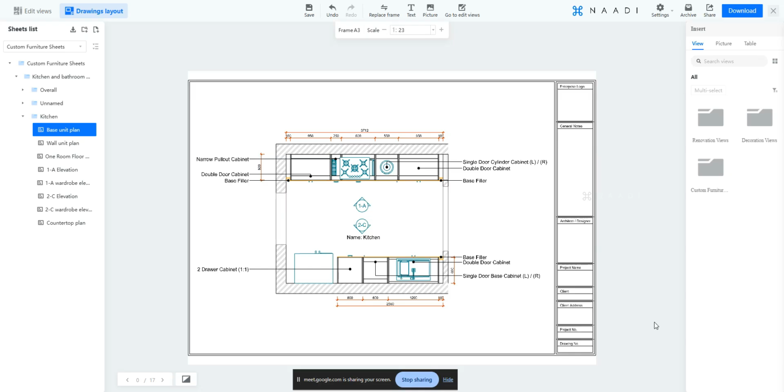So if your organization has a pro license ID, you can just share your 2D sheet template with us. That 2D sheet template needs to be shared as a DWG file. And if your sheet template has your organization logo, make sure that the logo is also a CAD logo. Please don't add it as an image, because the 2D sheet template in the backend can't read images. So make sure you have a CAD logo of your organization, place it there, and then share your sheet template.